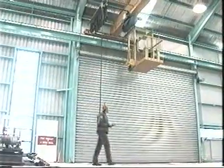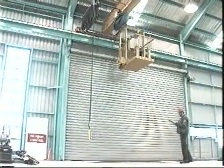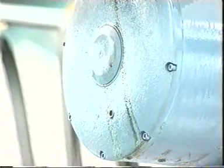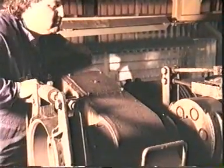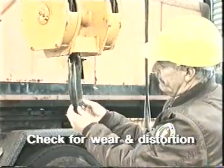Give the crane an overall check for any damage. Leakage of oil from gearboxes and hydraulic systems is an indication of possible wear or damage. Guards and equipment covers should be inspected to see that they are in place and not bent or broken. Check for any distortion or wear to hooks, ropes, and sheaves.